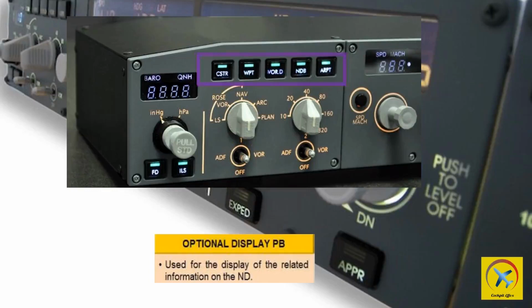When the VOR button is selected on, the VOR symbols are displayed a magenta color. Whenever the VOR symbols are part of the flight plan, the symbol is a green color. The VOR symbols are a white color if the to waypoint and blue when tuned by the FMGC, automatically or manually.